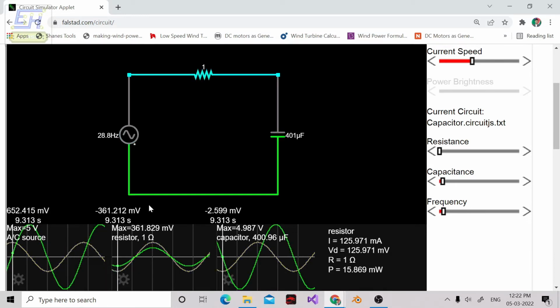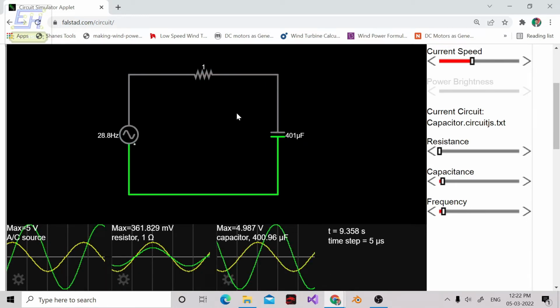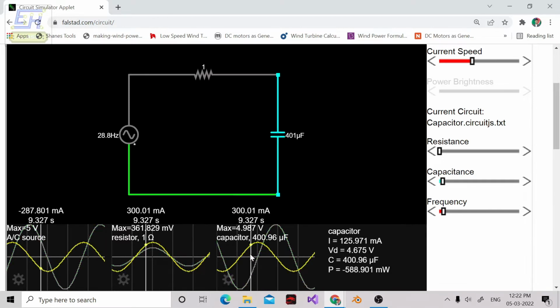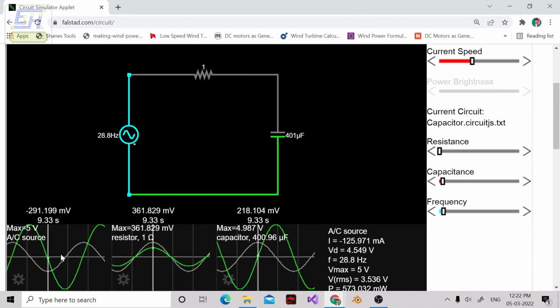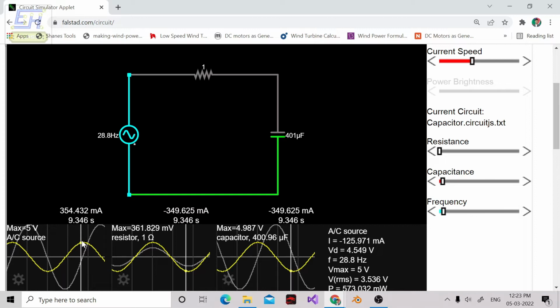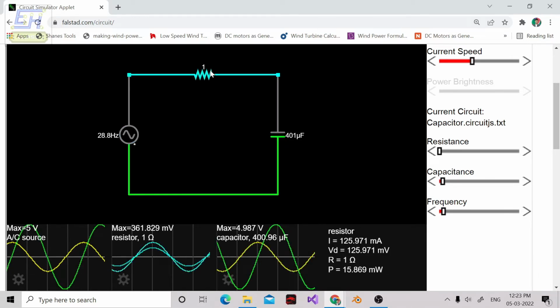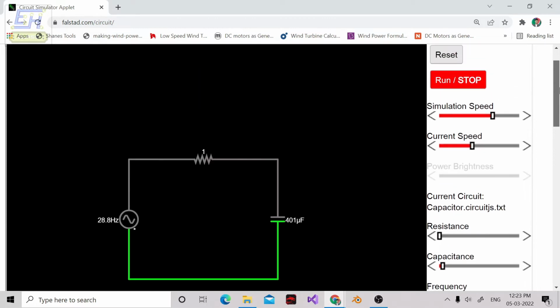This is because of the overall nature of the load which we have connected. Just see that our overall load is actually capacitive, because the capacitance dominates in the circuit. That's why you will see more capacitive effects at the AC source side, or a more capacitive load will be experienced by the AC source itself. But notice what will happen while we change the value of resistance.